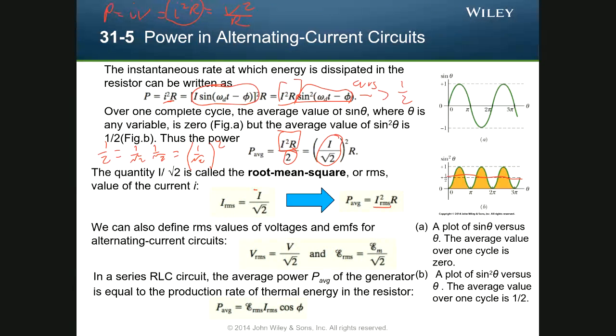We do have to keep in mind that the RMS value is not the peak value, right? If you peak at 6 amps, for instance, your RMS value will be lower, but again, we're getting an average power, right? Not peak power. And the peak power only occurs at one time, whereas the average gives you the average power over any time, okay? Or at least over one cycle.